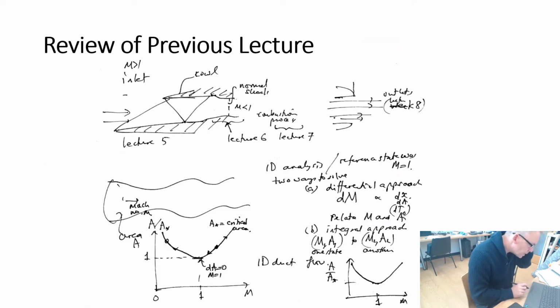Just to review the context of where we are, we kind of had this story of a supersonic jet engine. We discussed the inlet, the geometry of the inlet, this idea that we need to convert the supersonic flow into subsonic flow through compression, the presence of a normal shock.